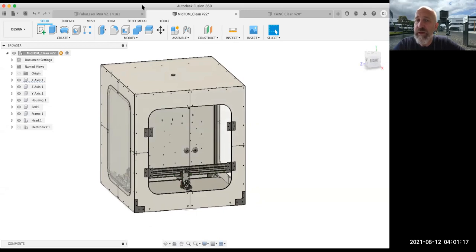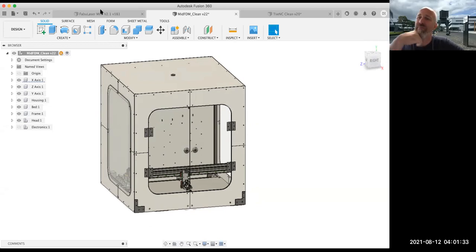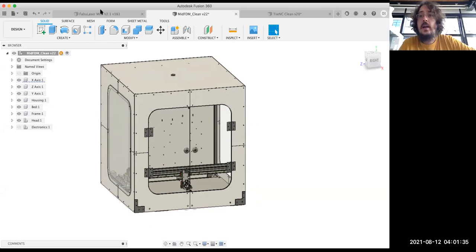Before you move on, that material, at the moment you've got it with a white surface on it. Does it also come with just an aluminized surface, or is it always that white color? So it comes in lots of flavors. You could have the natural color of the aluminum if you want, anodized aluminum, anodized with color, with special coating resisting to specific weather, another color. Yeah, it exists. It's a standard material, and it exists in a lot of forms.